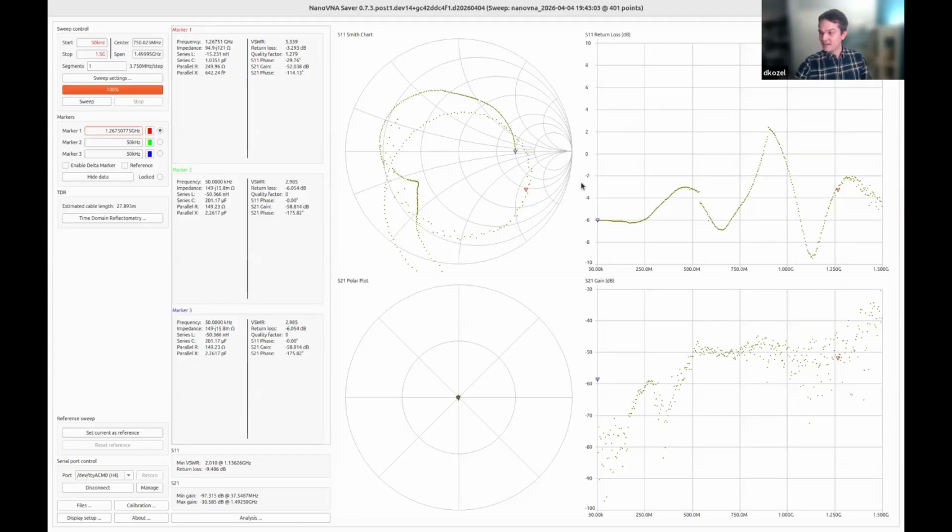The rest of it is, because it's reflecting back, we can see that it's not actually at 50, it doesn't measure as a 50 ohm device. It measures as something between 50 ohms and infinite resistance. Or, yeah, that's the right direction. Anyways, we're not getting a well-matched device.